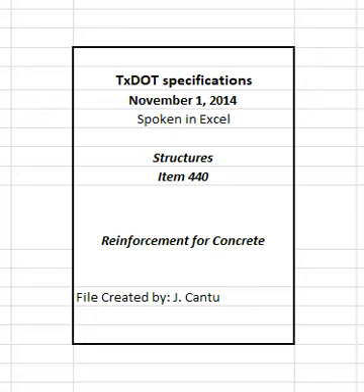These requirements do not pertain to miscellaneous welds on reinforcing steel as defined in Section 448.4.2.1.1, Miscellaneous Welding Applications. Calculate CE using the following formula. Do not weld stainless reinforcing steel without permission from the engineer. Provide stainless reinforcing steel suitable for welding, if required, and submit welding procedures and electrodes to the engineer for approval.